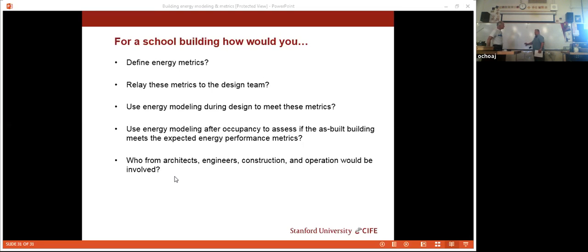Once we got our as-is model, what can we do to it to lower kilowatt hours per student or per square footage? That would be like adding solar power, insulation, sensors on our light switches, or maybe a combination of those, taking into account the cost and the pros and cons from one system to the next. We also have to run it over a period of time so that we can actually measure the improvements, collect data and be able to measure.